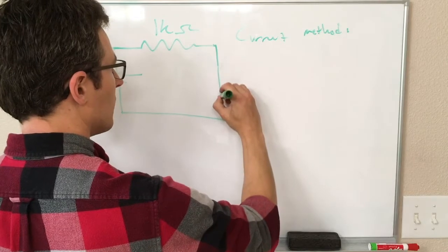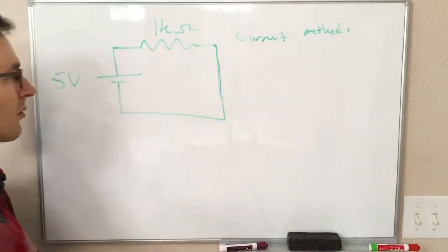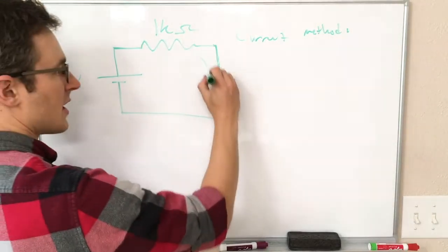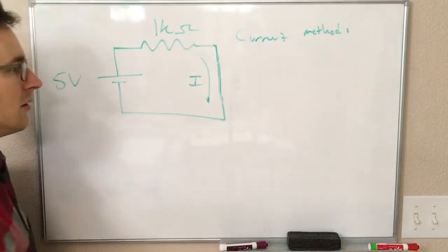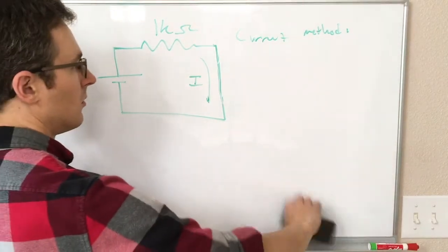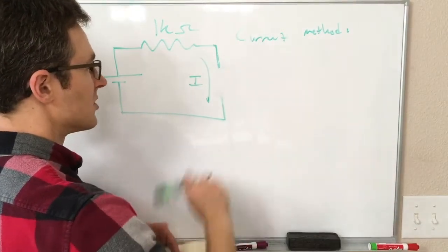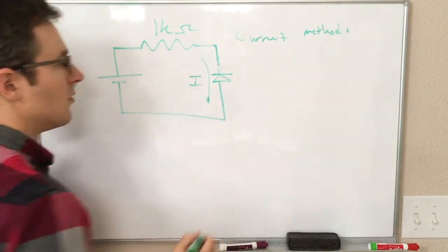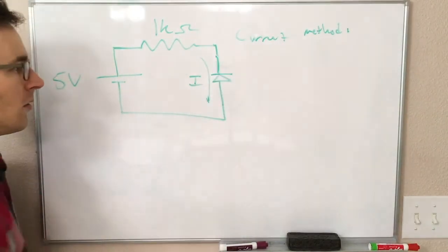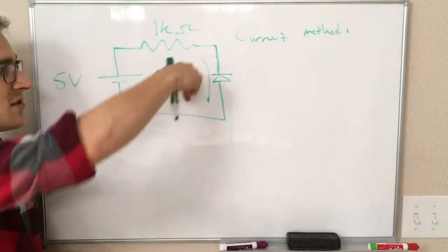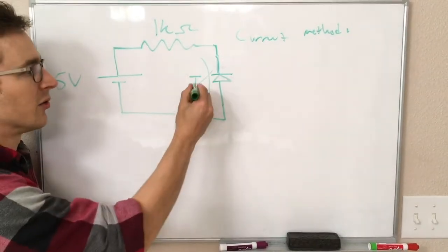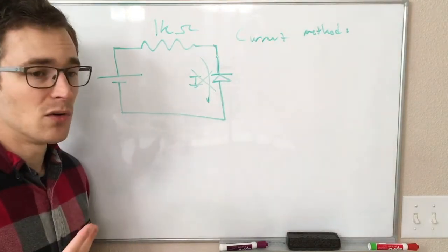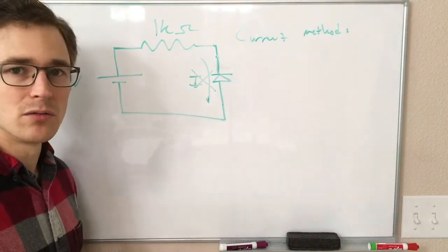So we're going to say, okay, well, now we can have as much current flowing through it as we want. So if we have a circuit that looks like this, we're going to have current flowing through it like that. Does that make sense for the diode to be on and have current flowing through it in this direction? No, it does not, right? Because this is in the reverse direction. We're not allowed to have current flowing through it. So it is not consistent with these facts that the diode is on.